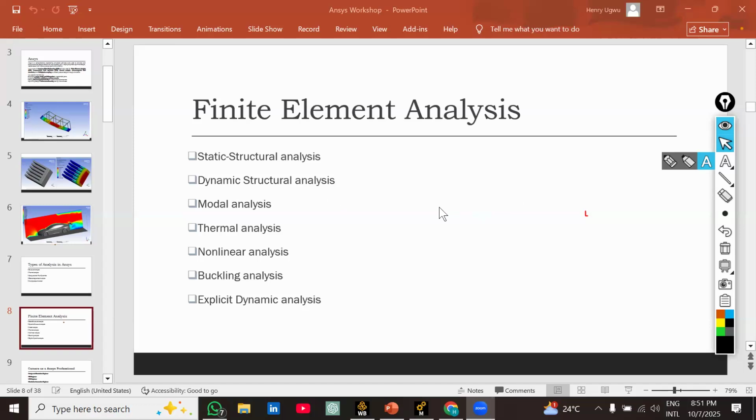The flower vase might be in that position for like 3-4 months straight without you moving it from there. So if you're carrying out an analysis on that shelf, you are going to carry out a static structural analysis, because the load, which is the weight of that flower vase on that shelf, which is on the wall, doesn't change with time. It doesn't change. It's static. It's steady.